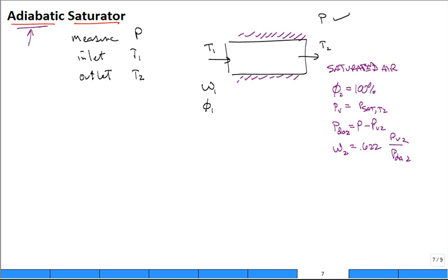If you're going to come out with saturated air, you have to supply to it. Not only do you have to supply moist air coming in, which is not saturated, and you're going to infer the relative humidity and humidity ratio of that moist air from these calculations, but what else are you going to have to supply to that box? You're going to have to supply some water. Often that is makeup water to help it become saturated air, and often this comes in as liquid water.